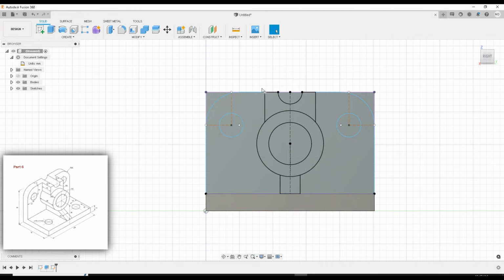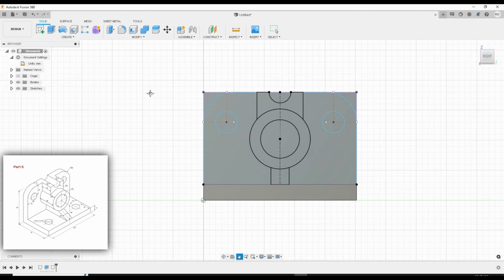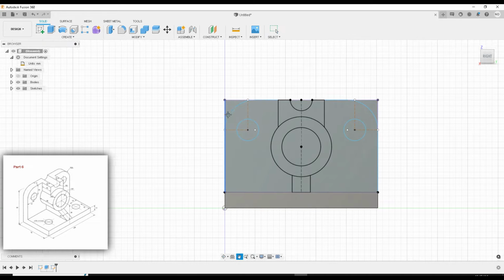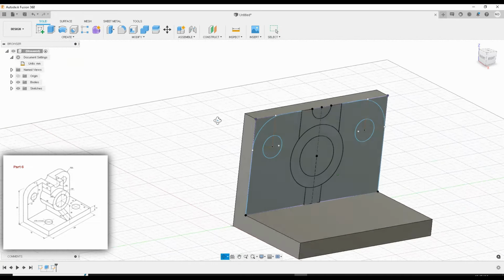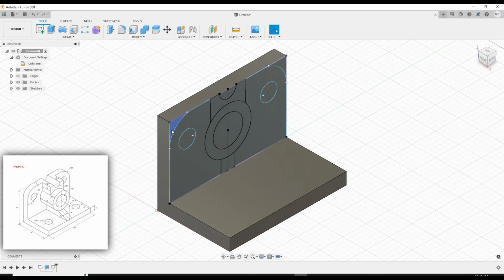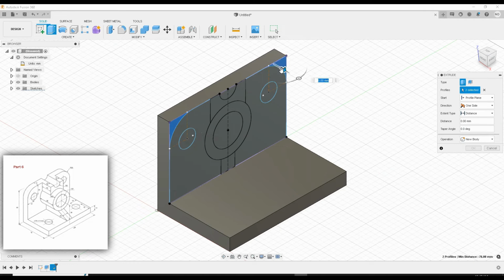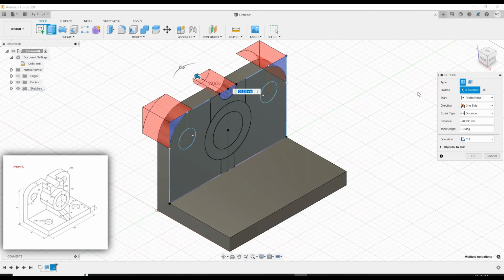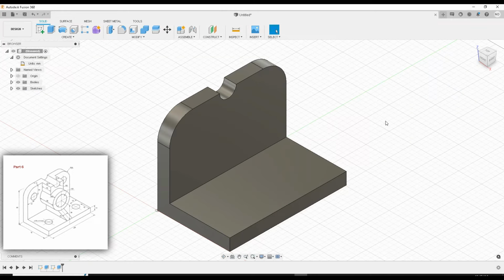So let's go ahead and finish the sketch. And now here's the fun part. We're going to start cutting away and developing new bodies. So you go back into isometrics, click on that. Now you see you want to make sure that the faces we created, we can highlight. Okay, you see that? So let's go to extrude, click that, click this one, this profile, click this one, and we're going to just extrude all the way through. Okay, cut. Press OK, and there you have it.